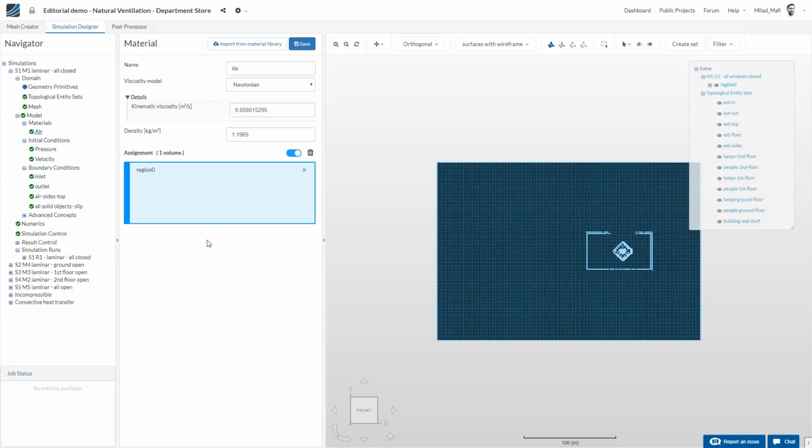Another question which was asked a lot of times is which file formats we support. Basically, first of all, we support in theory every CAD model which is a BREP or facet model, as long as you can export it to STEP or IGES. And this allows us also to import CAD models from CAD tools where we don't have a native import so far. CATIA is not a problem, Alibre is not a problem. You can import all the other tools, and this includes also PDMS tools for plant design and other stuff.